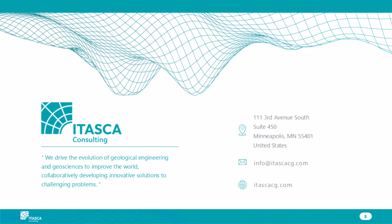Of course, if I have 2 kilometers of soft ground, I'm not going to go down 2 kilometers. But in many cases, you can push the model down to a certain level that you can consider bedrock, and then you can use the outcrop motion itself without doing any deconvolution, like you would need to do in case you cut the model to a certain depth, let's say 20 meters, and then you want to input the ground motion from an outcrop, in order to consider that the shear wave velocity at that depth is not the one that you had when you recorded the outcrop signal. I'm not sure if this is answering the question, but essentially, I take the outcrop motion, convert it into shear stress or normal stress in any direction that you want, and that's it.